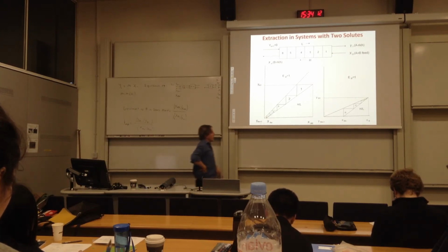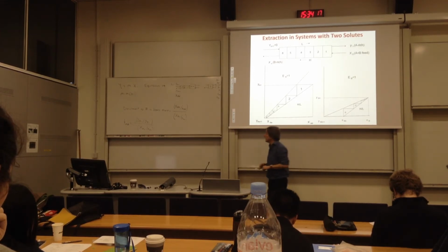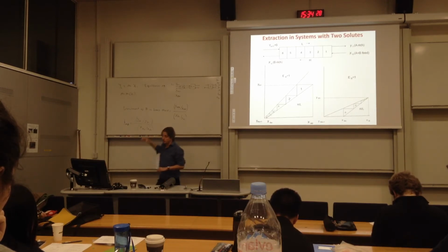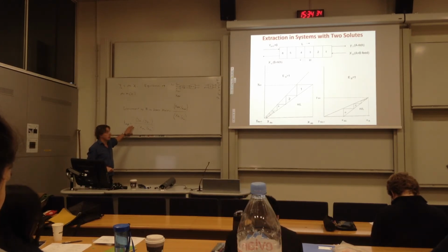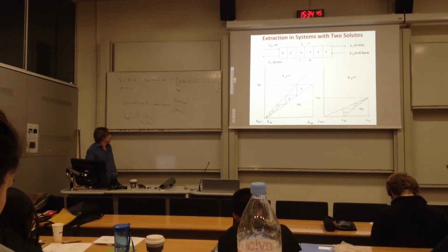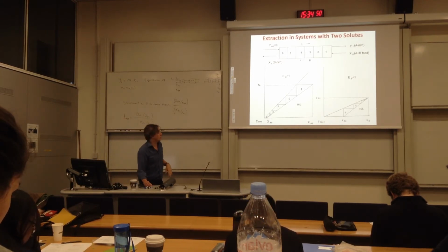Well, you still have a large transfer of B to the organic phase, and that will show us a large value here of YD from stage 1. So basically, the issue here is that the decontamination factor cannot be as good as we want. It can be rather low now. Okay. So this is just an example to give you an idea how these numbers, enrichment and decontamination factor, can be applied to assess a system.